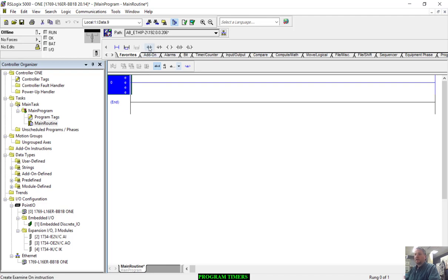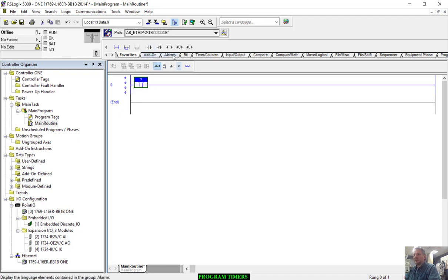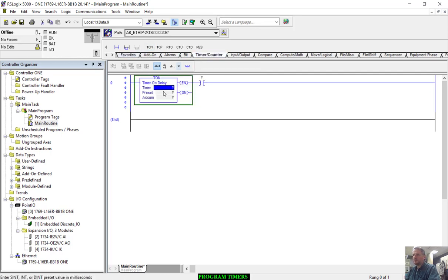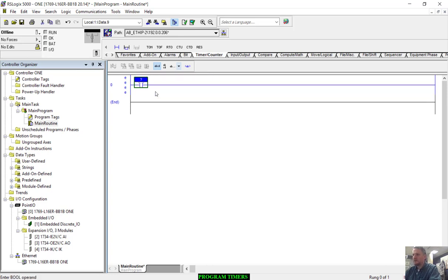So what are we going to do here? We're going to come in here. We're going to add a contact, and then I'll come over to timers and counters. I'll incorporate first the timer on. Oop, I didn't plan on it. Timer on is considered to be what? An output command, not an input command, so it's got to go where? It's not here, but here. I'm not sure why I tried putting it there.